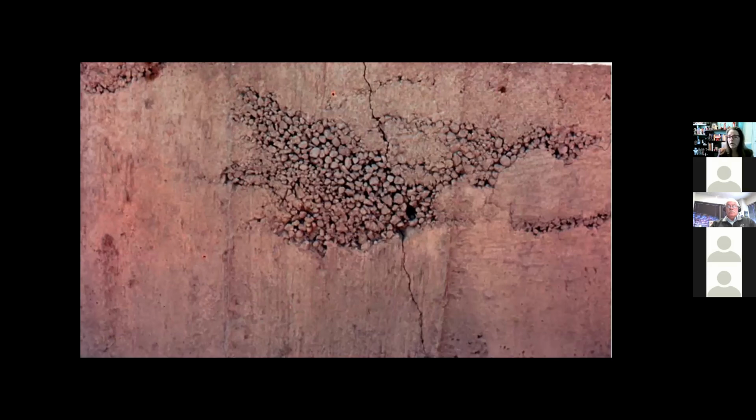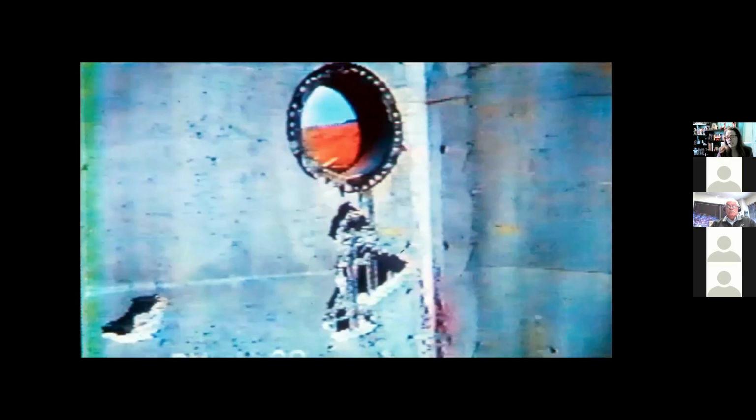They obviously left it in service. This is actually a bridge abutment wall, so it's been in service for many years. And you also see honeycombing often wherever there's a window or a pipe or anything that could cause any type of restraint of getting the concrete to flow readily around. This is where SCC would be a great idea, whether or not it's necessary.